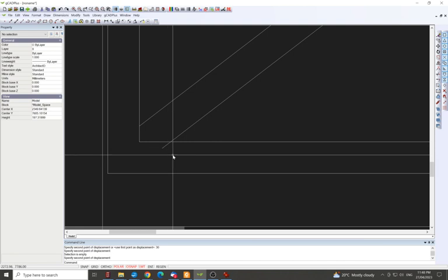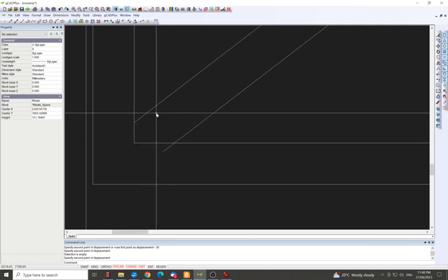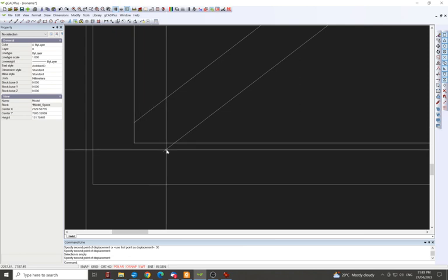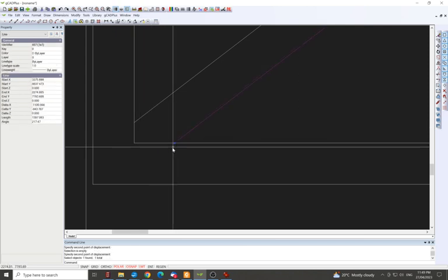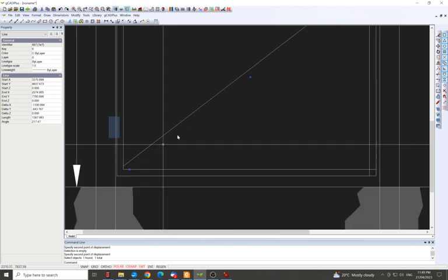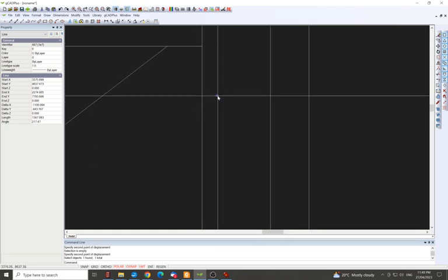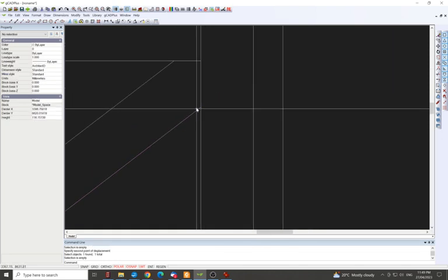You can see it's overhanging a bit here. I think because they did make that 15mm and I thought it was 30. I don't know what's going on. It looks a bit wider there, so I think it's got to do with the way the miter cut affects the distance. It's not square. Just because you get 15 there doesn't mean that it's going to be 15 out there, because it's on the diagonal as it comes in. If that makes sense. I don't know how you'd explain that any other way, but so there's our brace.